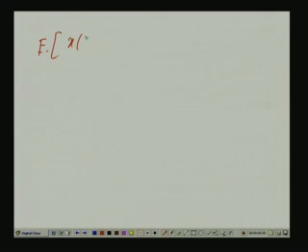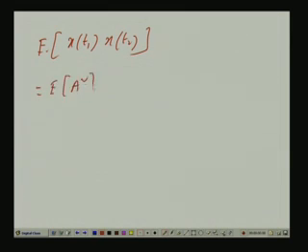So, you then take two time points t1 and t2 and multiply. Obviously, there will be a squared term, okay. That will give rise to a separate E of A squared, because of the reason I have already explained, because A and phi are statistically independent. So, the joint density will be written as a product of two individual densities, one with respect to A, that will come with a square integral. So, that will give rise to E of A squared.